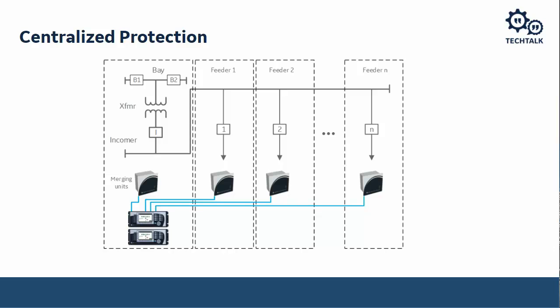We can add a second relay and offer redundancy, which is something we typically don't have in lower voltage systems. Now we'd have a redundant system that is offset. The relay itself can provide you control. You can operate breakers from away from the breaker. You're not doing anything in front of the breaker, so that increases personnel safety, versus when they operate the breaker standing in front of the cubicle. The other nice thing is, since these merging units are bringing back everything via fiber, there is no possibility for open CTs. So additional safety is added by doing this.